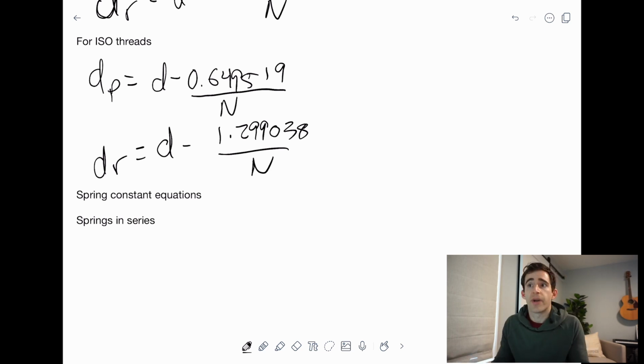Like so. One of the common applications of screws and bolts is holding two parts of materials together. You want to clamp two things together. The applied load of the situation would then put the bolt or screw in tension. In these scenarios, a fastener is often tightened to as high as 90% of the proof strength in static loading and 75% in dynamic loading. The goal is that if the fastener is sized correctly, it will not break in service if the fastener doesn't break while being installed and tightened down. So if you tighten it down to a high proof strength, it's not going to break. The preload is going to properly set that.